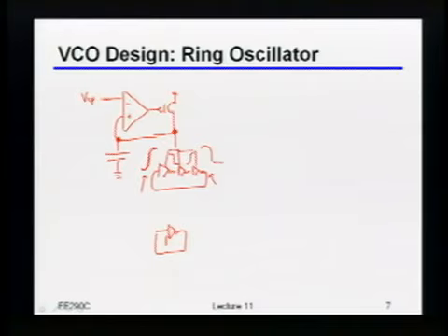So the thing to keep in mind with all these oscillators, and this is true even in the analog domain, is that you really want those edges to be sharp relative to your frequency, just to make sure the thing really does spin the way we want it to. All right, one other question.